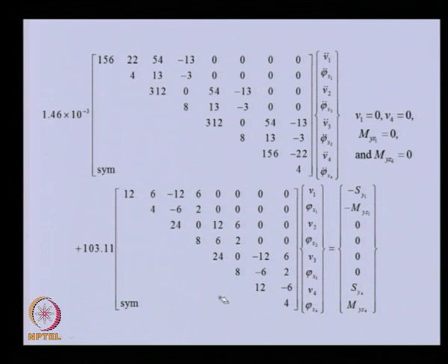Similarly, this is the assembled stiffness matrix. In the reaction force vector, the shear force and bending moment at the common nodes 2 and 3 will cancel each other. The ones at nodes 1 and 4 will not be 0 unless specified by the boundary conditions of the problem.